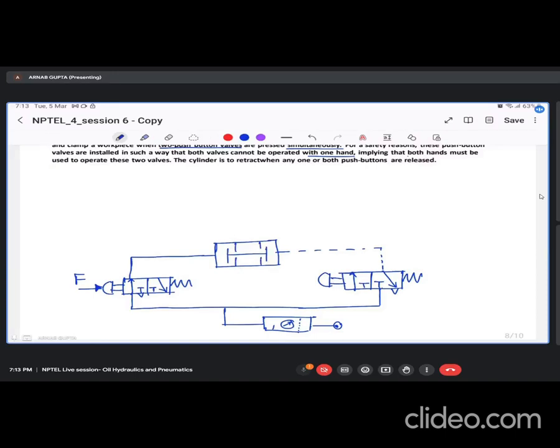Okay, so you can name this as P and D, like pressure and exhaust ports. Here also pressure and exhaust ports, and say 1.1, 2 and 1.4. Both of these will be giving a signal. As you can understand, this one is logic 1, this one is logic 0, since there is no flow.